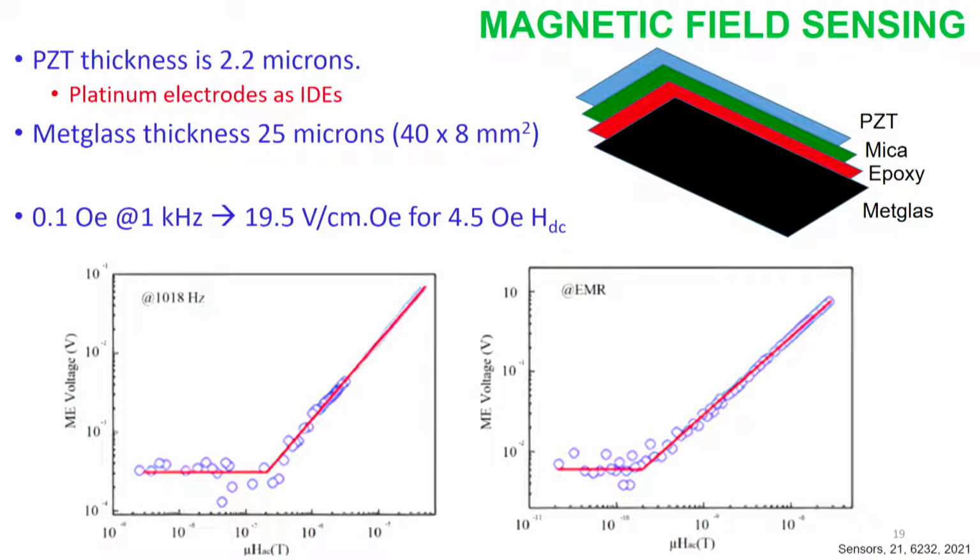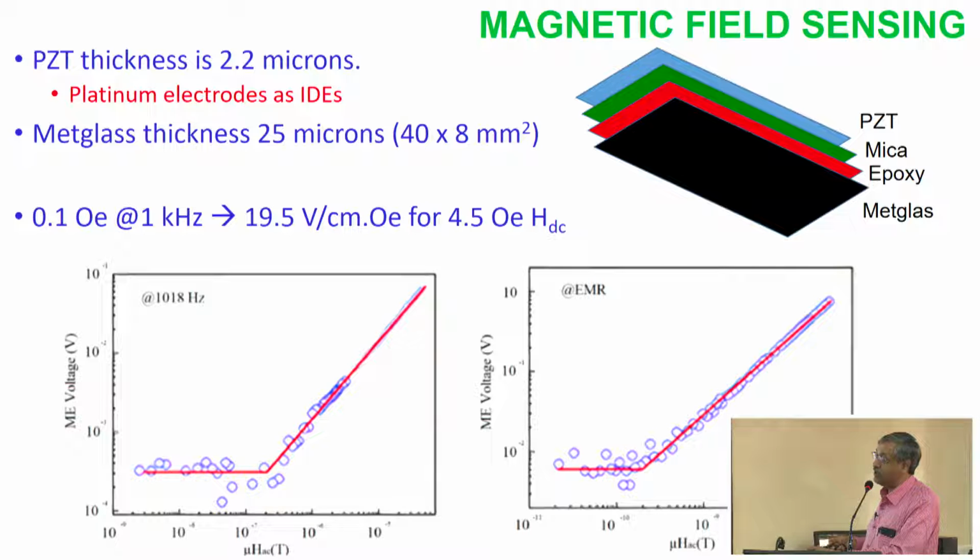Another one is that the noise is going to be very high here. If you neglect this and go into this particular region, the noise is going to be very large. Therefore, the signal to noise ratio becomes very low. So here also it is not advisable to operate. Even though you have this, you are advised to operate only in this particular region. So one should choose a proper region to operate the device. Maybe for other purposes it may be very low here, for publication purposes it may be done, but for the device you have to fabricate, you need to have proper linearity and other things.